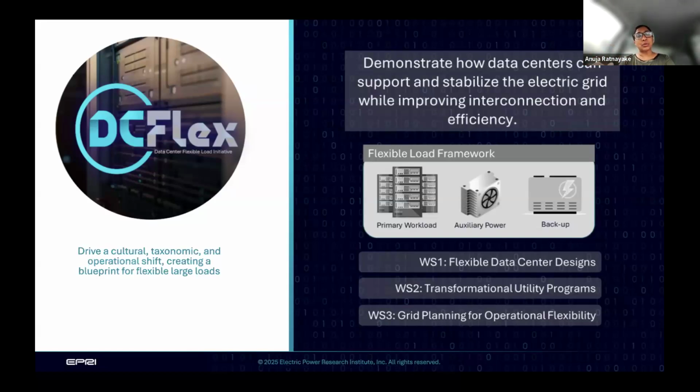Normally, a brand new transmission upgrade is in the range of about 7 years. Generation and new additions can be anywhere between 4 to 10 plus years, depending on the type of new generation we want to build. So, for example, combined cycle facilities used to be about 4 years. In the new supply chain constrained world, that number has changed. But if you wanted to have a multi gigawatt nuclear facility, we were talking about more than a decade easily.